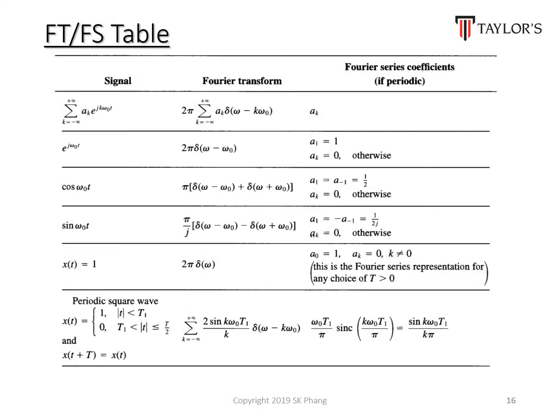And sometimes it is quite difficult or tedious for us to do the integration, especially if your signal is not just a square signal. Let's say your signal is something like a sine signal, and then imagine you need to multiply the sine signal by the exponential signal. Alright, I write it here. The formula was x(t) multiplied by e to the negative j omega t dt.